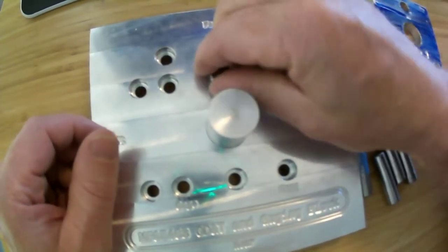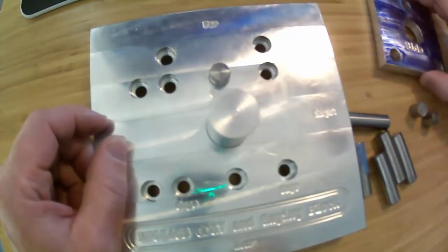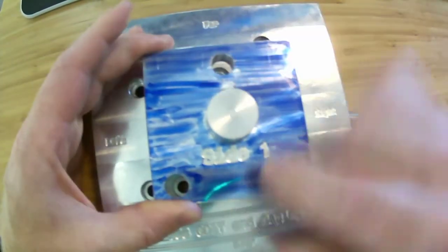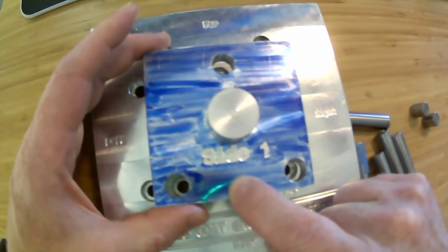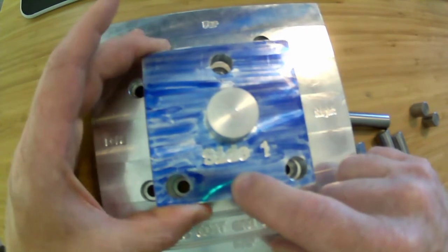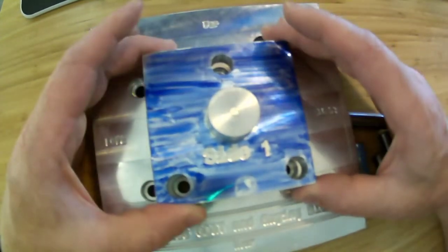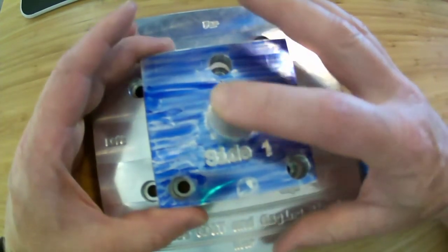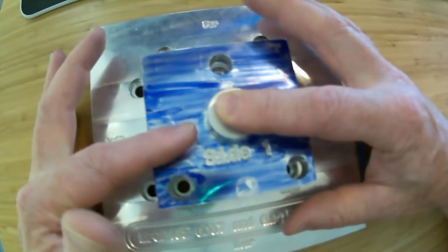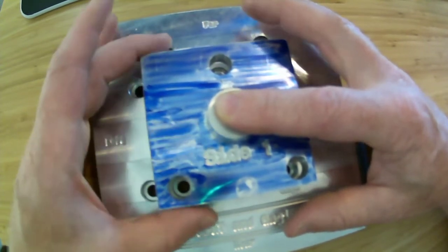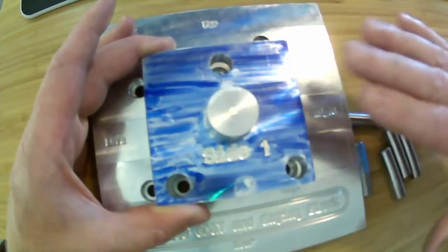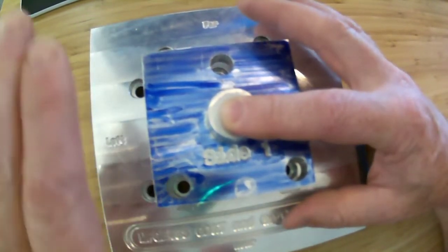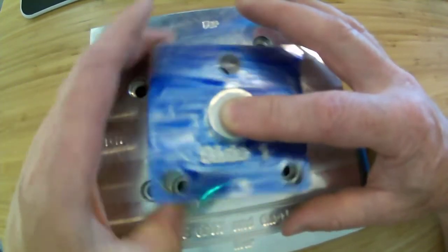Well, I could put in a small pin, and then I know, oops, that was the wrong place to put that small pin. Let me put the small pin down there. So now I know where the part is being located on this plane. It's being located on that pin. And so now it will spin. Maybe that is a better solution, but it might not be. So this is a more deterministic solution because I have now eliminated 4 degrees of freedom with this pin. It can't translate in X or Y, and it can't rotate around X or Y. And then the little pin down here has limited the translation in Z, but it can still rotate around Z.